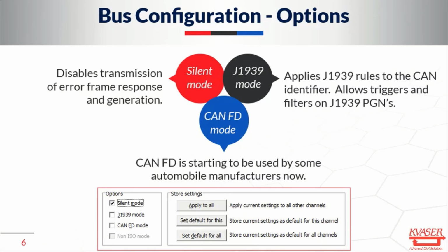And then we have CAN-FD mode as the third option here, and CAN-FD mode is obviously selected if you're working with a CAN-FD data bus, which is not real popular, right? Well, it's not real commonly used right now, but it's certainly coming into the industry rapidly. We're just going to give all examples of standard CAN, what's called classic CAN at this point. We won't talk much about CAN-FD, but this device does fully support CAN-FD. It would change a few other things about this presentation, but we can get into that maybe some other time.